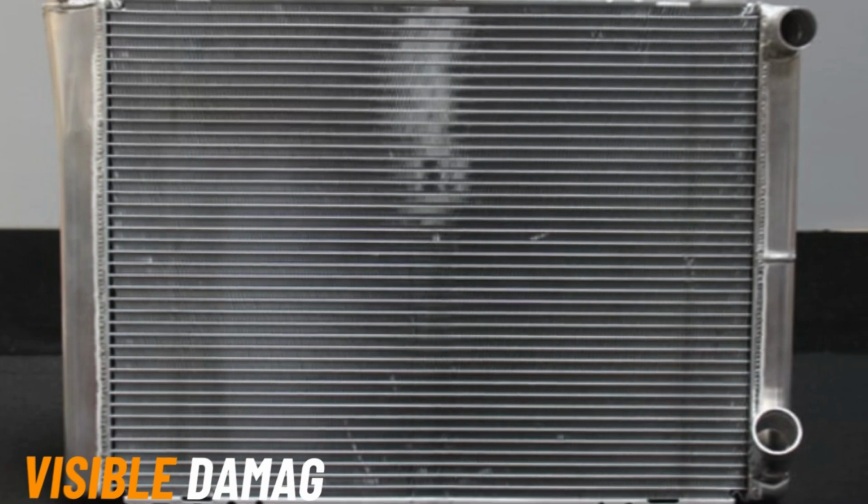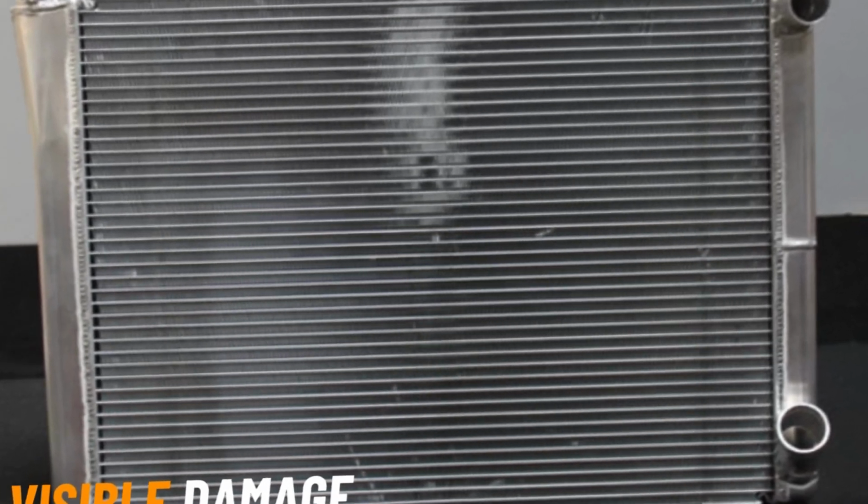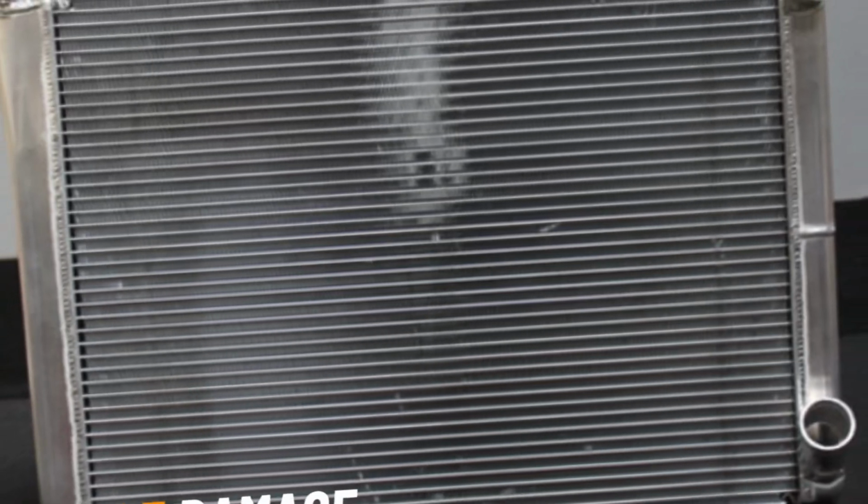Number 4. Visible damage. Inspect the radiator visually for any signs of physical damage, such as cracks, corrosion, or bent fins. Damage to the radiator structure can impair its ability to cool the coolant efficiently.